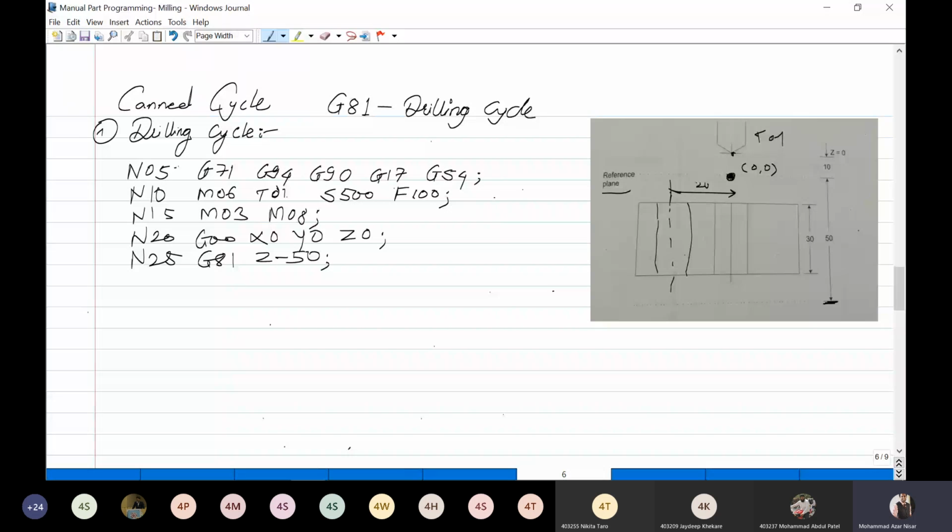This is how it will drill the hole up to the depth, and you have to take R equal to the extra, which is 10, R10. This is not related to radius, it is related to the breakthrough distance of the tool. Breakthrough distance of the tool, R10.